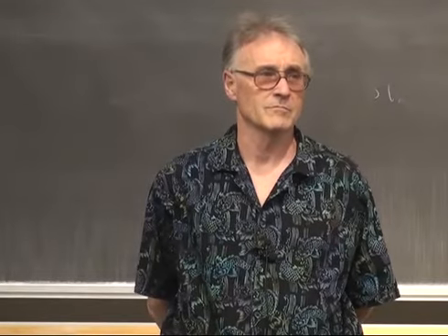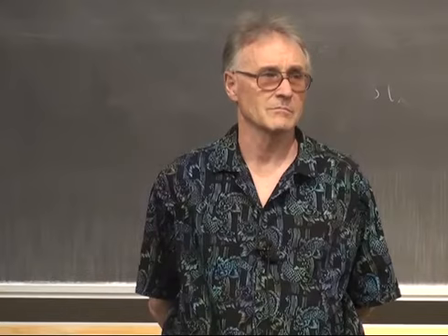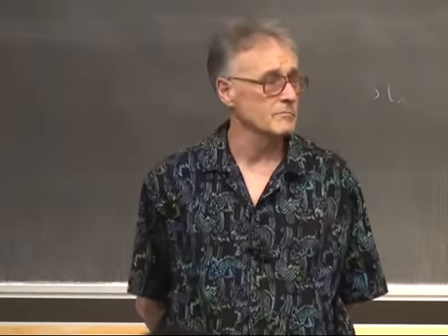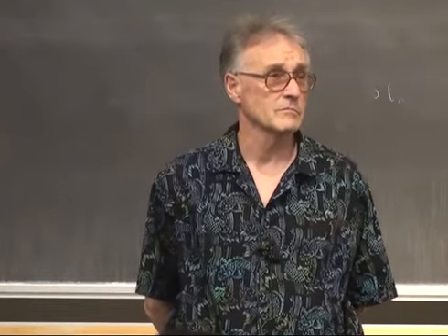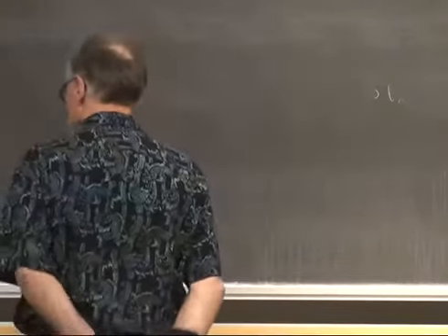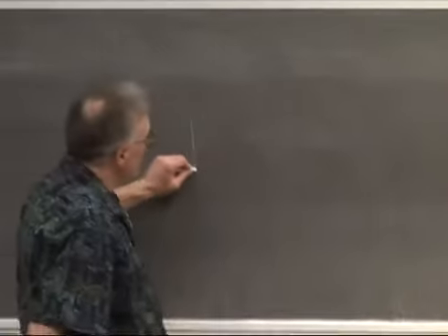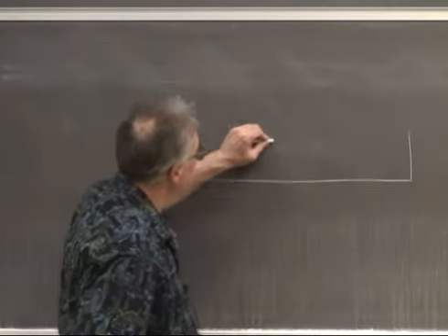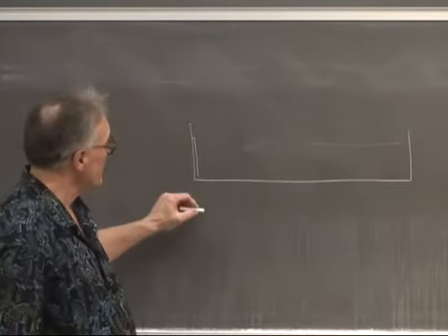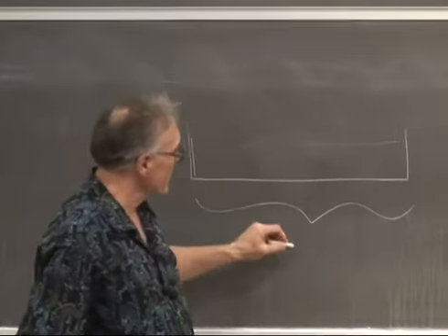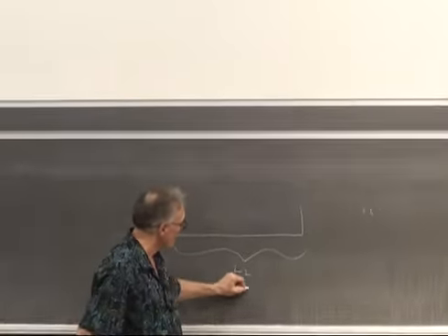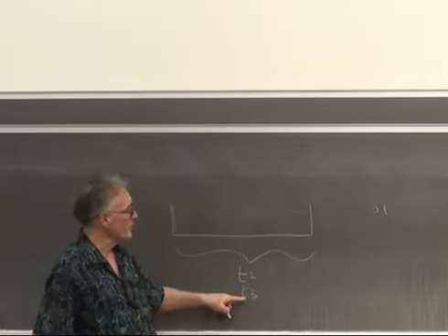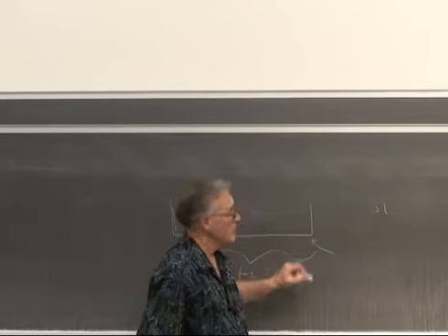Yes? So PID, like the output is like a control value? PID output is a float, yeah. So how do you recommend converting that to a duty cycle? Well, as I've said before, the basic duty cycle from 0% to 100% depends on your timer interval. So you're going to set up some timer, timer 2 or timer 3, your choice, to some interval which is fixed.